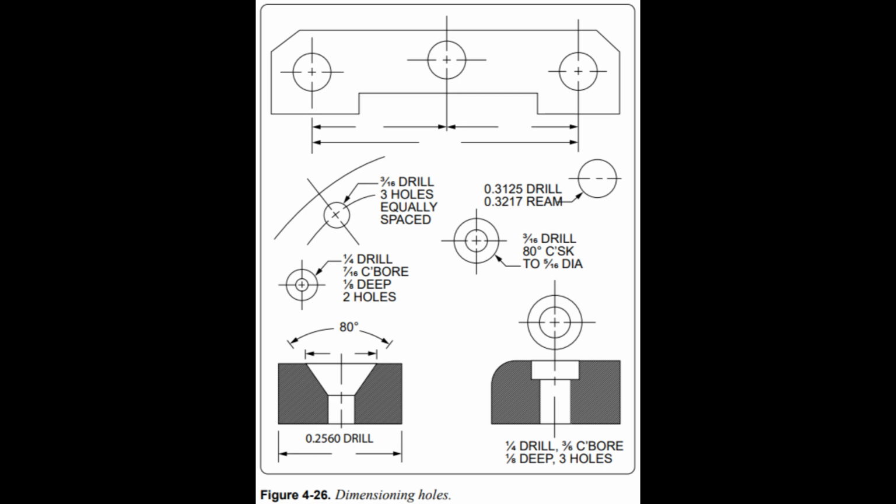The dimension of an angle is indicated by placing the degree of the angle in its arc. The dimensions of circular parts are always given in terms of the diameter of the circle and are usually marked with the letter D or the abbreviation DIA following the dimension. The dimension of an arc is given in terms of its radius and is marked with the letter R following the dimension. Parallel dimensions are placed so that the longest dimension is farthest from the outline and the shortest dimension is closest to the outline of the object.